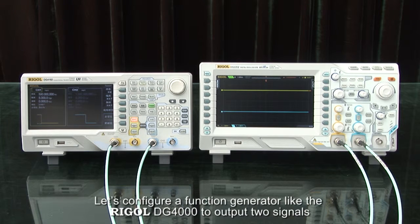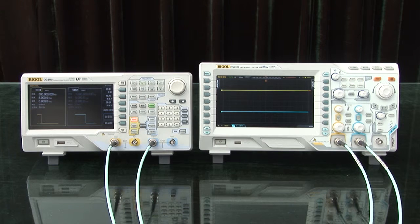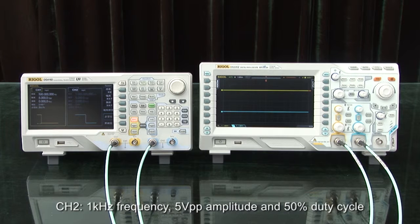Let's configure a function generator like the Rigol DG4000 series to output two signals. Channel 1 will be a 500 Hz, 5 volt peak-to-peak with 20% duty cycle. And channel 2 will be 1 kHz, 5 volt peak-to-peak with a 50% duty cycle.